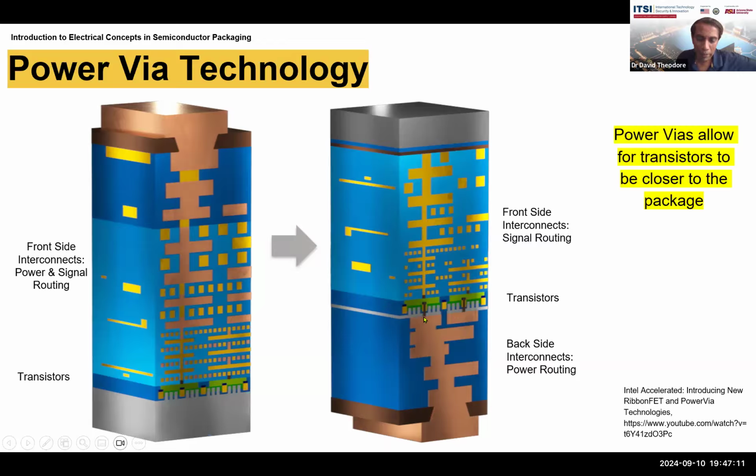So actually what's happening is, the thin gray layer, so here you see the gray silicon is thick. What you do is you thin this silicon down to a much thinner layer. So this layer in most wafers could be 400 microns, which is almost half a millimeter. So what you have to do is you thin this down. You could thin this down to 100 microns or 50 microns. People are trying to push it thinner and thinner.